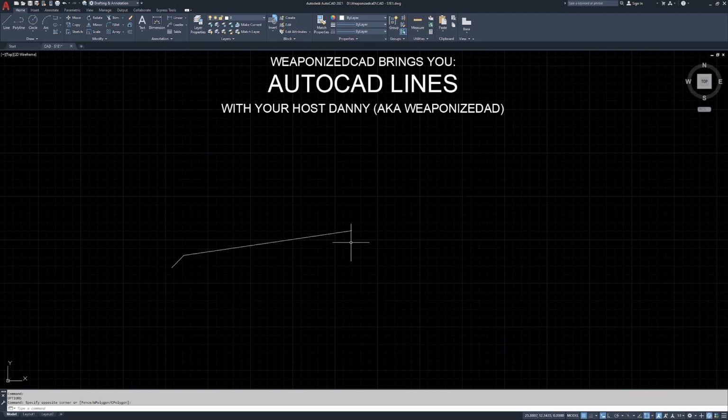We've drawn two line segments. Let's go back to line. You know what? We're going to use the keyboard this time. Line command, L, enter. Now, what you just noticed, I'm going to escape out of that and show you again. When I hit L, this is called the dynamic input. So while you're moving your cursor around, there's this ghost command line that's attached to the crosshair.